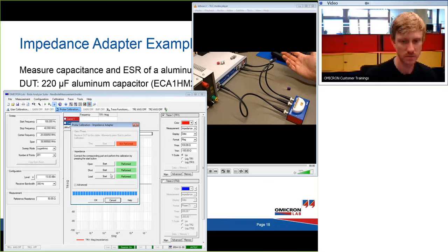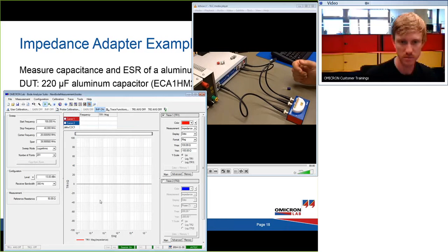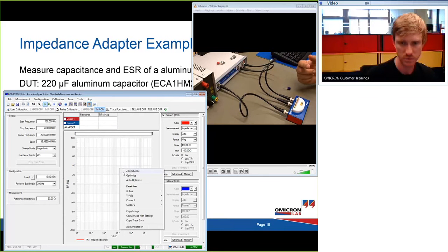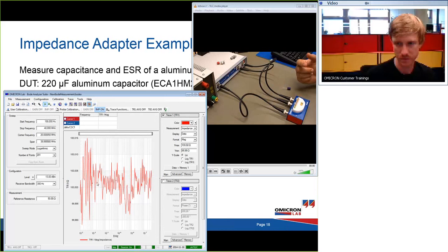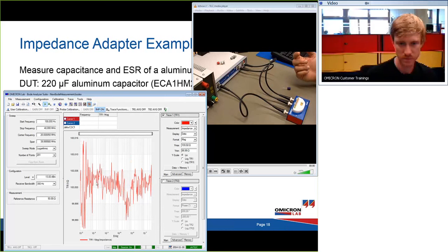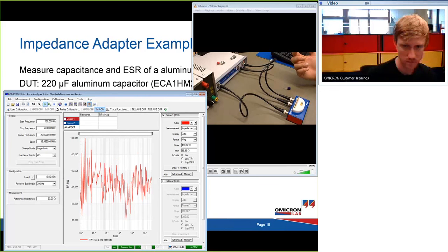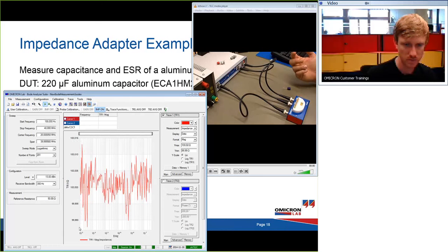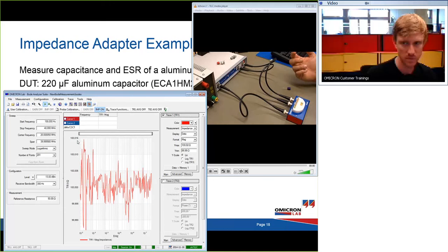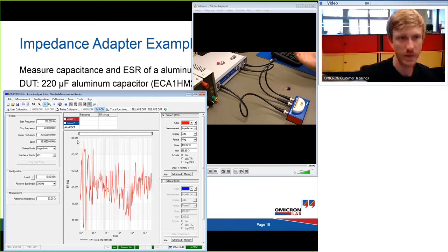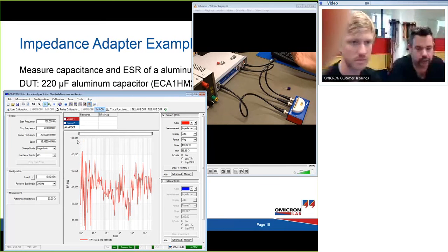When Florian has finished the calibration, you can just leave the resistor in. We are using a 100 ohm resistor for this calibration, so we can now check if the calibration was successful. What looks like a crazy curve on the screen is in fact showing a very accurate 100 ohm, because the entire diagram is from 100.015 ohms to 99.99 ohms.